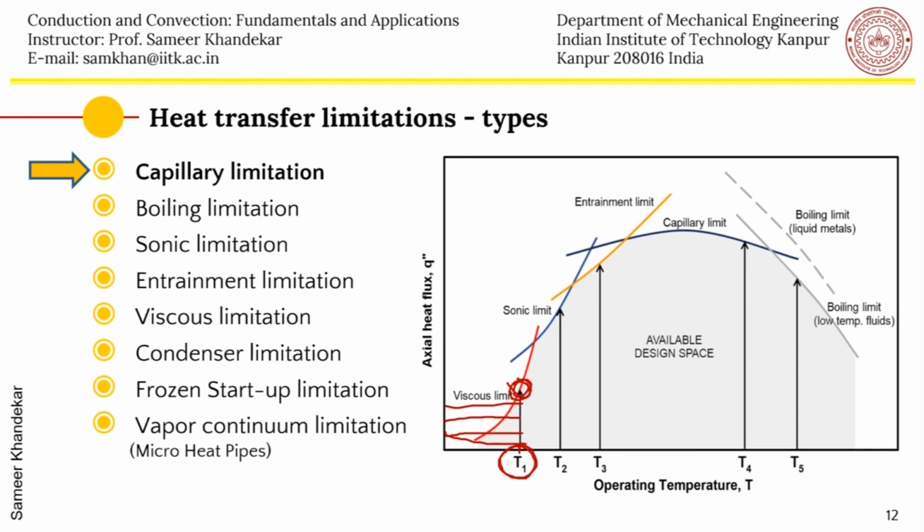So basically what you do is you increase the evaporator power by a certain amount, let's say 5 watts or 10 watts. The temperatures will rise. You will bring them down to the operating temperature which you want by cooling down the temperature of the condenser. The condenser is also usually over designed so that you are not limited by the capacity of the condenser, which itself can be a limitation sometimes. But we are assuming that that is not there in this particular case.